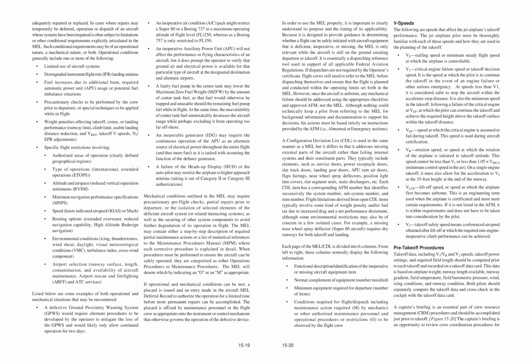An inoperative auxiliary power unit, APU, will not affect the performance or flying characteristics of an aircraft, but it does prompt the operator to verify that ground air and electrical power is available for that particular type of aircraft at the designated destination and alternate airports.